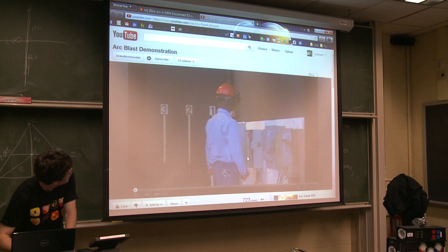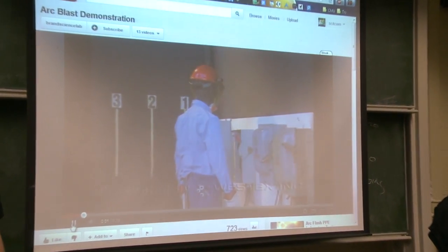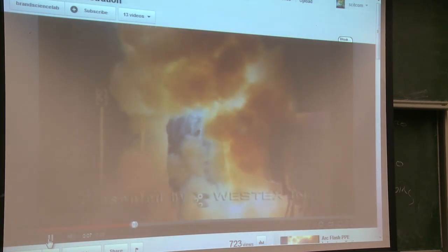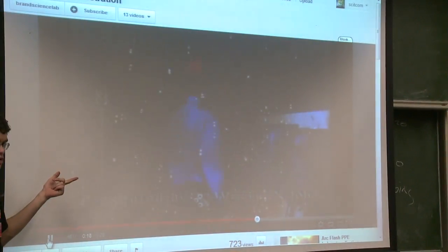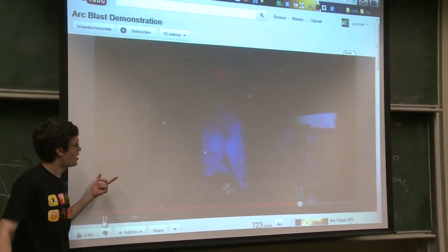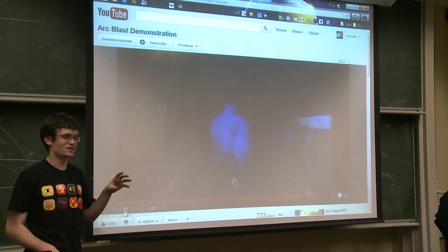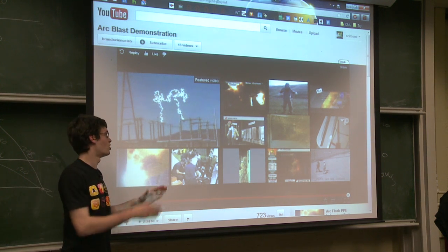Here's video number 1, and hey, look, there's my mouse. This is what happens when these circuit breakers malfunction. Or not circuit breakers, but disconnects. So if you turn it on and there's a spark, or you turn it off while there's a load going through it, it is possible and maybe even likely that a small explosion like this will happen. And the reason that they are made as a solid box, except for the front, and all the wires are inside, is so if this explosion does happen, all of that energy is directed straight out away from the wall.